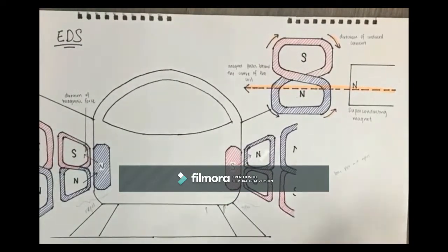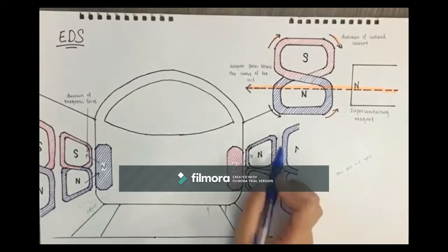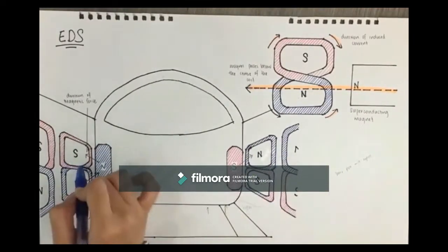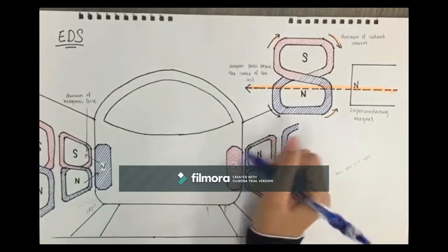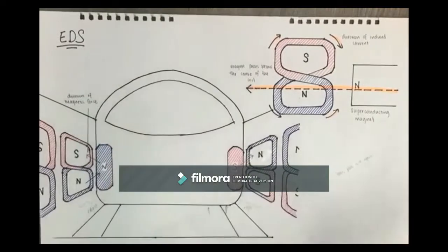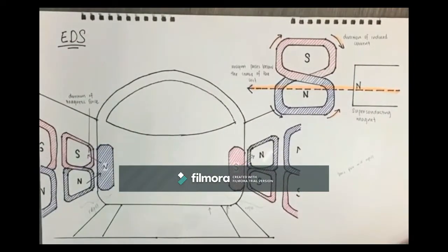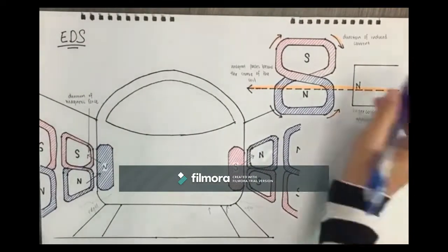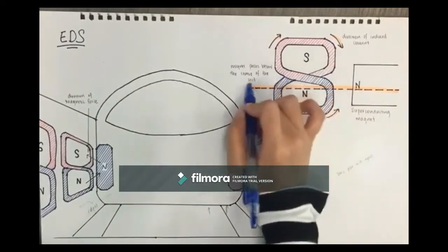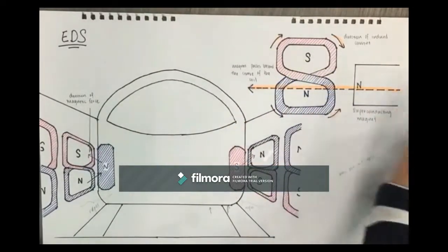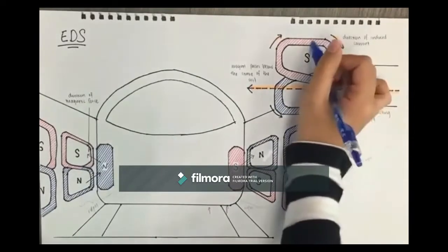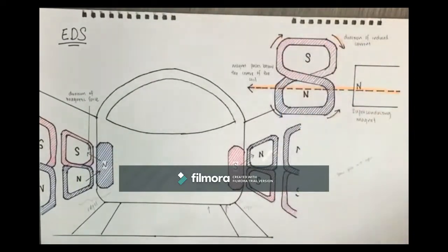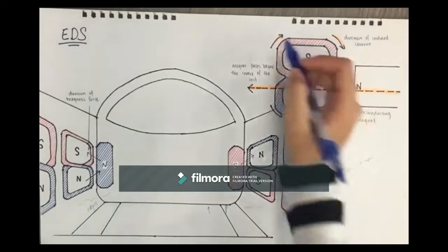The train travels in a guideway which has a series of H-shaped coils on each side. When the train travels by with a high speed, the superconducting magnets on each side of the train will induce a current on the coils. The trick is that the superconducting magnet passes below the center of the H-shaped coils, thus the magnetic flux change in the lower half of the H-shaped coils is greater than that in the upper half, and the current as shown in figure is induced, generating a magnetic force.